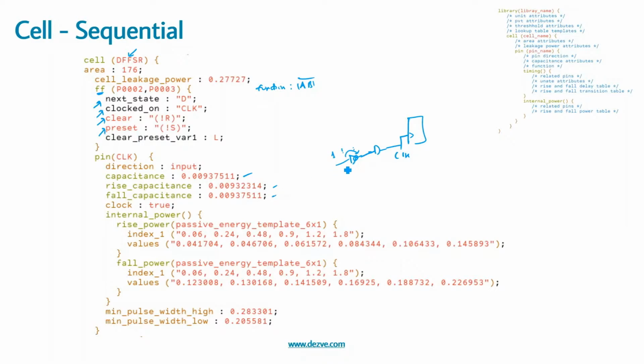So depending on that, during the propagation delay computation, we would actually consider the delay based on the transitions. Suppose this node is going into a fall, then we might want to consider a fall capacitance charging time, and based on that we compute the delay. So this is the pin, and in most of the cases we have seen the pin definition.